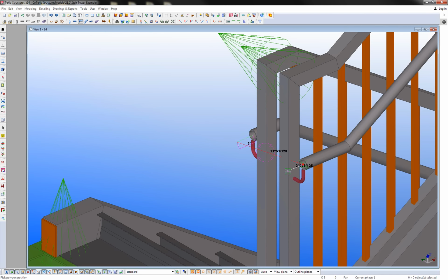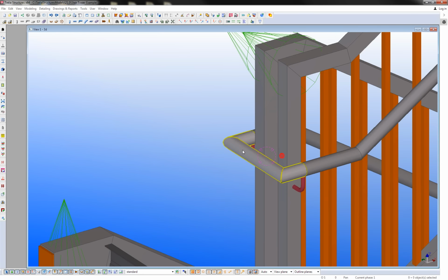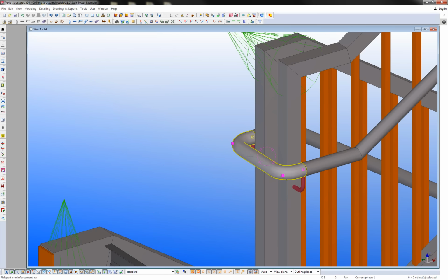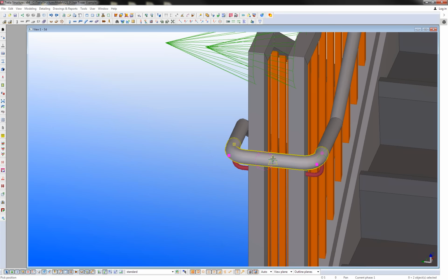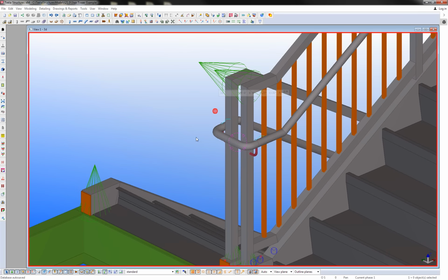Come out 3 inches. And obviously you can make these dimensions whatever you like. So I'll come back 3 inches again. If I'd like, I can put a radius on here. You can do any type of finish you'd like on there. And then if you want, you can split that so that one section will be shipped with the upper rail and one section will be shipped with the lower rail. Make sure those are welded in place. You always have to remember that Tekla is very shop fabrication and erection driven, so you want to make sure you add welds where welds are required.